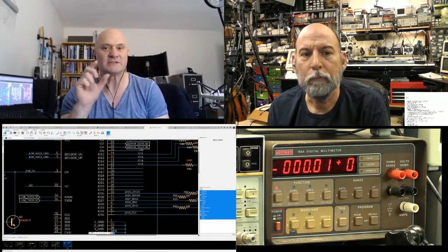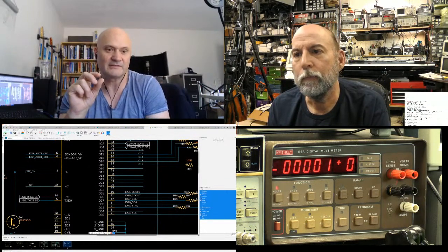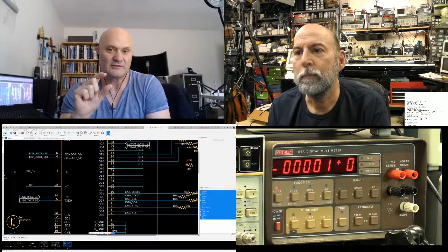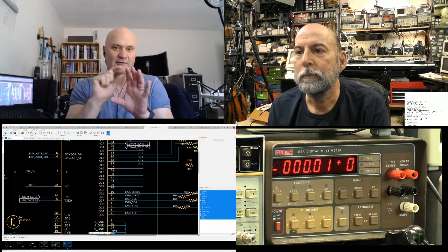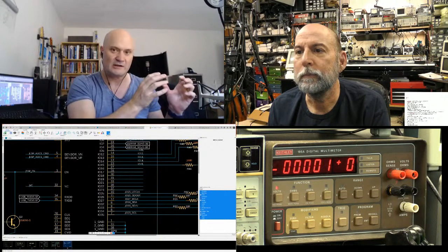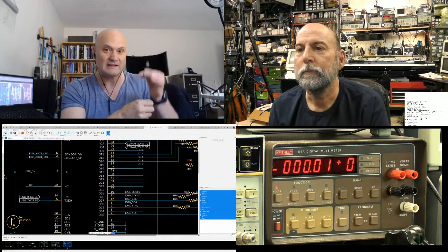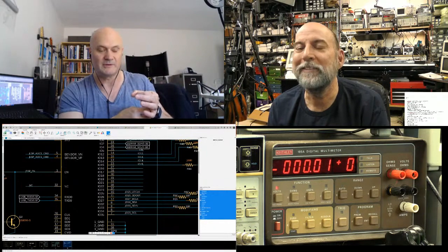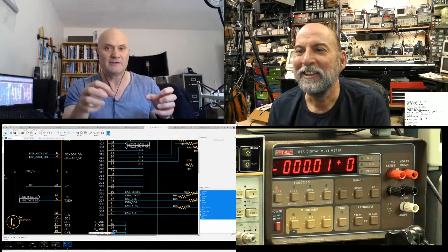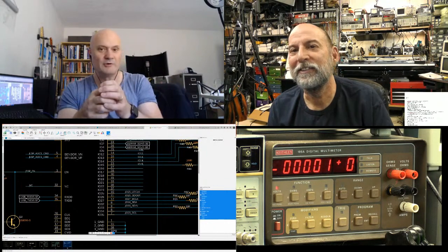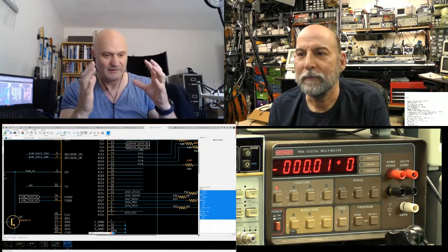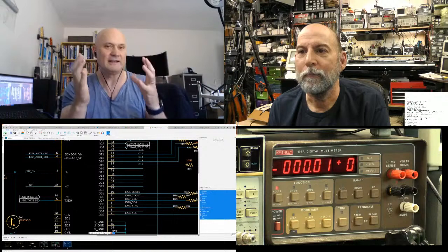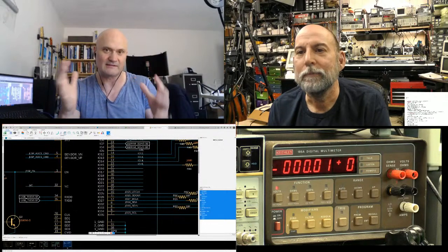So imagine I have designs with potentiometers. I can actually make my potentiometer in the CAD library for electronics. So when I place it there on a board and then go to an enclosure, it can automatically cut a hole in the enclosure for me right where I put it. And if I move it, the hole will move with it, right? That's the kind of thing we should have been doing years ago, but finally there's a product that can do this kind of thing. It's Fusion.